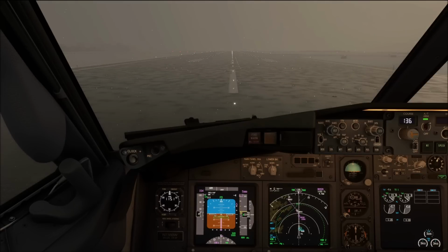So, there is a slight difference there between the 737 NG and the MAX, but we are only going to cover the NG right here, right now. In freezing conditions, with conditions likely to cause fan blade or engine core icing during taxi, such as freezing fog, heavy snow, freezing rain and blowing snow, do the following.